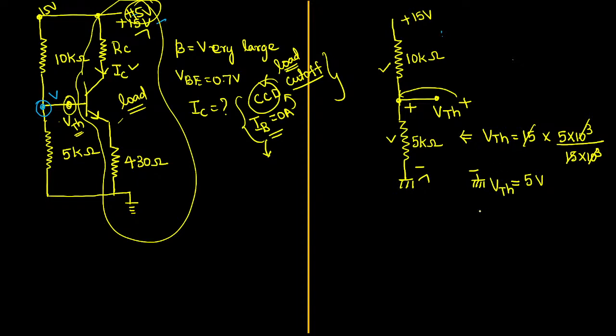Then what is the value of RTH, sir? How will you calculate RTH? While calculating the RTH, as usual, same procedure. Step number 1, identify the load. Transistor is acting as a load. Step number 2, remove the load from the load point. Yes, it has been removed.